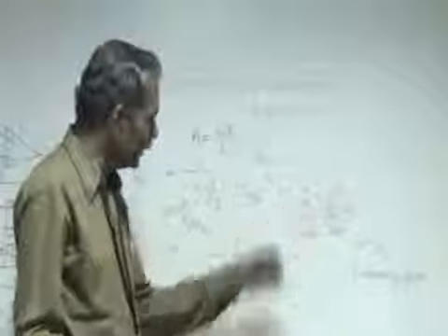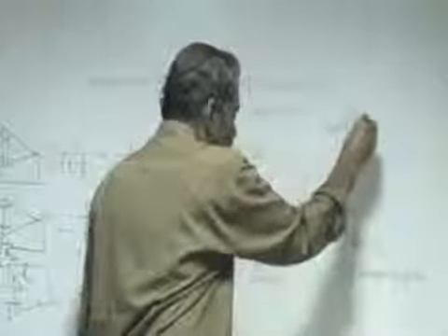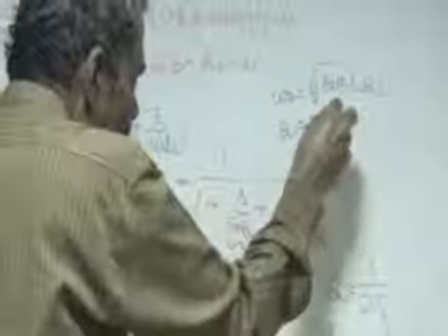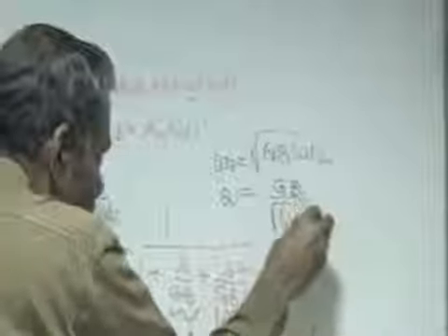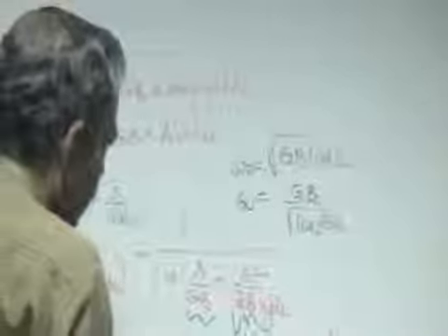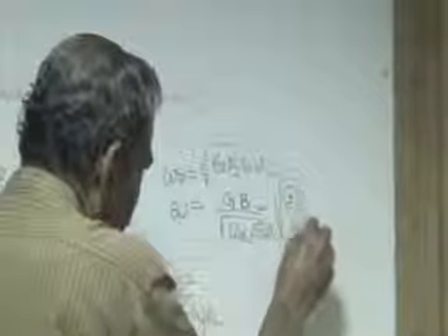Q in this particular case you can evaluate by equating omega naught to the square root of GB into omega D2, and since omega naught into Q is the gain-bandwidth product, Q is going to be GB divided by the square root of omega D2 into GB.